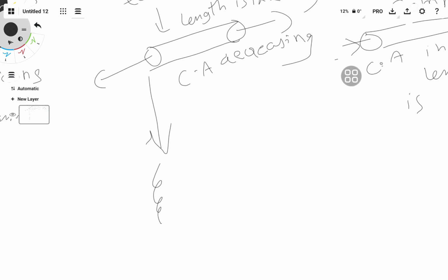let's say we have a hook like this, and it basically has a weight of 5 Newton, cross sectional area of 0.15 centimeters square, and an extension of 3 centimeter, which is basically how much the force stretches it and pulls it down from the original length. Let's say original length is 5 centimeter and extended length after this is 8 centimeter.